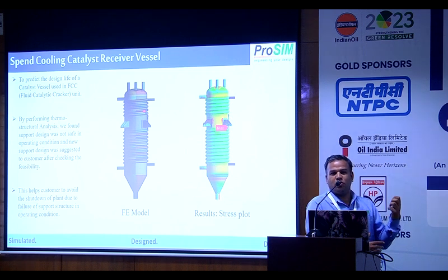One challenge is the cooling effect, a sudden drop in temperature from 600 to 250 within a span of time. The transient timeline also has to be captured, so the simulation effects have to be taken care of. We have to apply the true stress strain curve. The data will be received as elastic plastic engineering stress strain, which has to be converted, because it has to capture the instantaneous overall area for the true stress strain. If you go with engineering, then you get the wrong results.